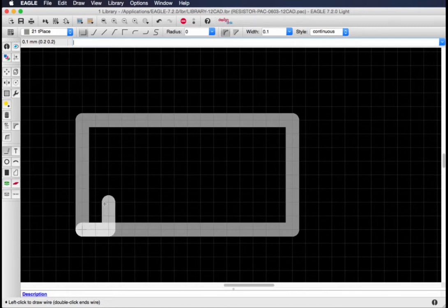And then when I'm done, I can press escape. And now I've created the physical layout of the resistor. But as you remember, we need to create copper pads that are 0.3 millimeters of length and 0.8 millimeters of width. Now to do that, if you look in the left toolbar, you can see here it says draw a surface mount pad, or SMD. Now that is the copper pad that you see in your resistor.